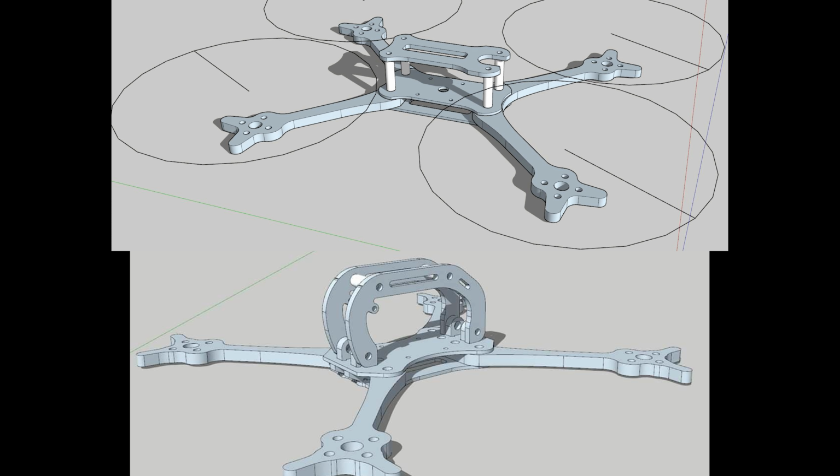So basically, yes, we can confirm that you need fewer filters with this, but how much you actually need depends on what gyro you're using, because we've seen huge differences with different gyros. I fly a gyro that needs just one single dynamic notch, not the default Betaflight with 2 notches.